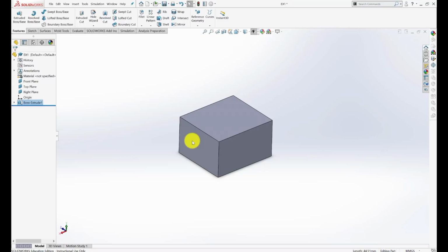Okay, now one of the main characteristics that I want to talk about in terms of parametric design is that we created this part, and this part exists now as a shape that's 30 millimeters tall, but we really don't have any clue how wide it is or how long it is. Now I can come over to the design tree, and I can notice something important. Next to this sketch there's a minus sign, and that means that the sketch is not fully constrained, which means the computer had to make its own choices about what dimensions I wanted, and that's not good. I want to be in control of all the dimensions.